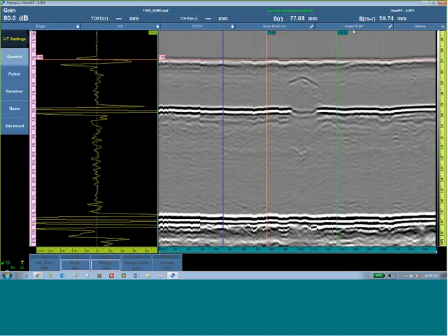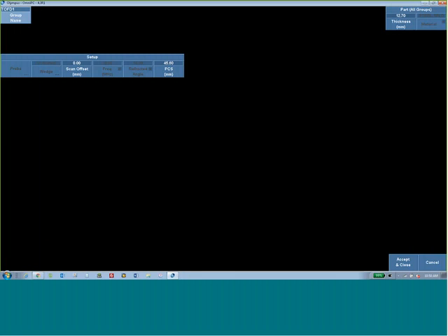Right-click on the interactive header for the setup configuration. I can see that the PCS value here was calculated as well. Because the lateral wave arrived at a similar time of flight as the calibration block, I am not going to change this value.